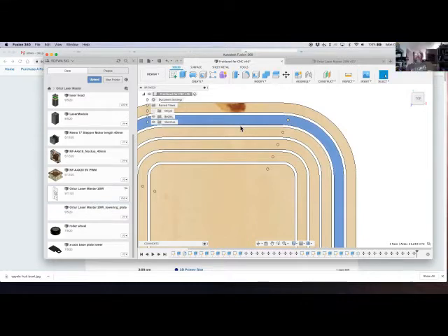So why would it do it twice? It seemed to be machining one side and then the other, even though it was a 1/8 slot. So it's a 1/8 slot, a 1/8 bit, and it still wanted to clean it one direction, clean it the other. Correct. Interesting. Okay. And then if I brought it in too much as 2D, then the holes would come in as bitmapped holes, which was problematic.